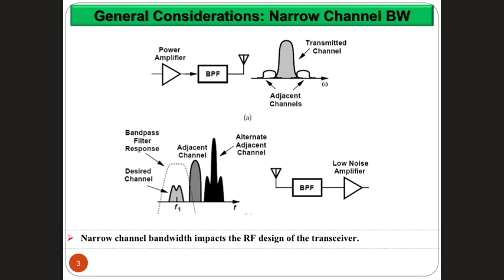then we end up with the ratio between the center frequency and the bandwidth as a high ratio. And as you know from your studies in electronics and circuits, there is something called the quality factor of a filter, and that quality factor of a filter is proportional to the center frequency, FC, divided by the bandwidth. So the higher the center frequency, the higher the quality factor, the higher the bandwidth, the smaller the quality factor. Okay? Now, what does the quality factor represent?